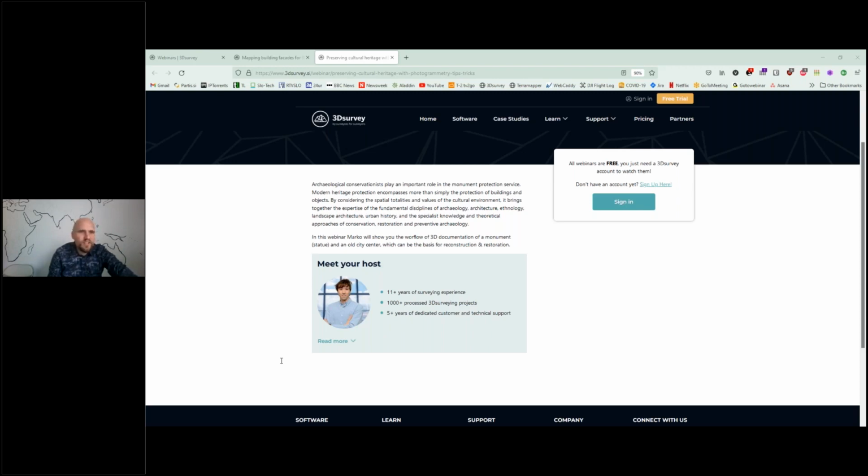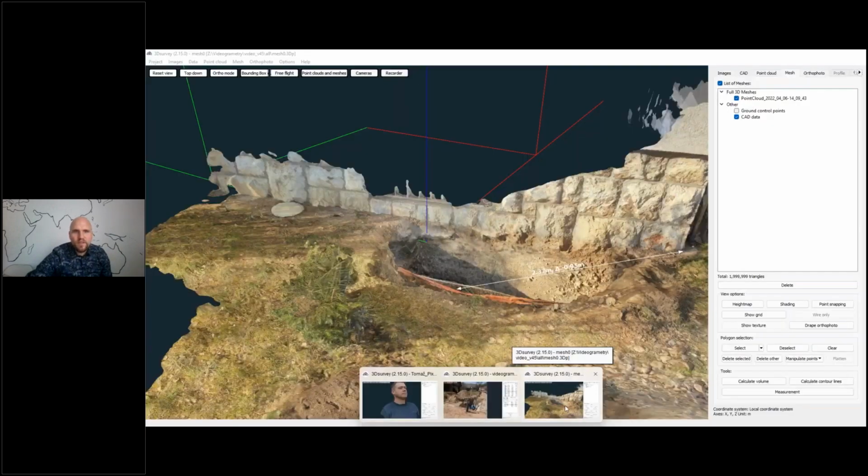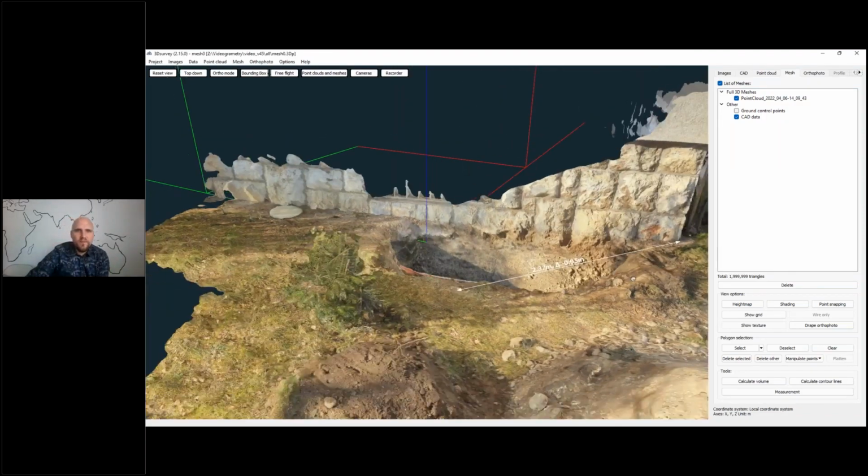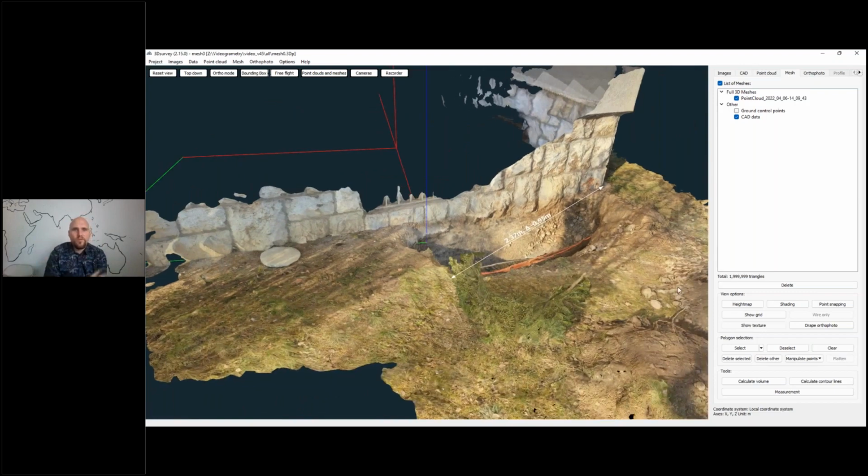You can also use photogrammetry instead. It will take you longer to record the images, but the images that you will get will have higher resolution. Now the question remains whether you need that kind of high resolution, because if you're recording a facade of a project, even for that second example that I was showing you, this one, here we recorded from, I don't know, a 2-meter distance. So we had 2 megapixel images. If we had 20 megapixel, even here we had a millimeter scale resolution in the end. So even that was plenty.